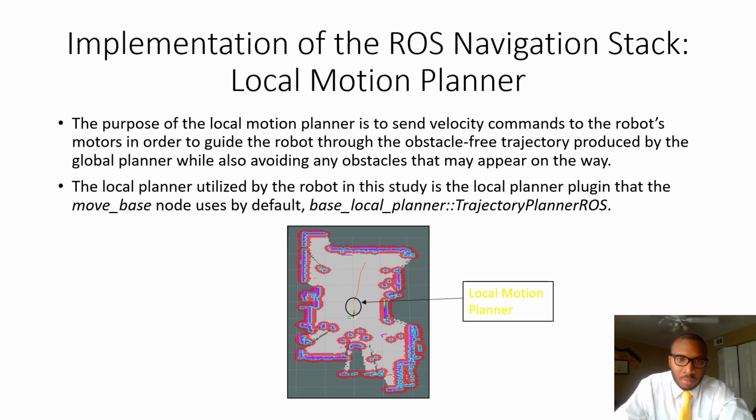And what we see below is actually the same 2D occupancy grid of my workspace, but it also has all of the obstacles that were spotted within the map inflated. So you see all of these inflated spots where the obstacles once were. They're now inflated so that the robot knows, okay, I need to avoid these obstacles as much as possible. And actually, this picture was taken as the robot was attempting to complete a navigation task.